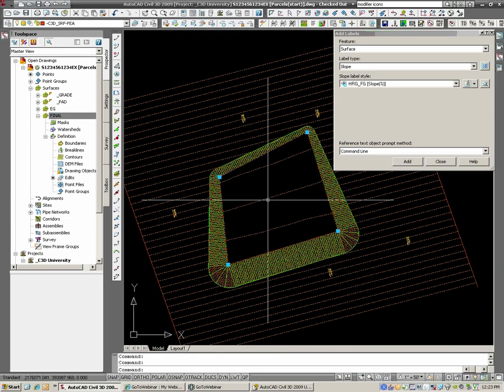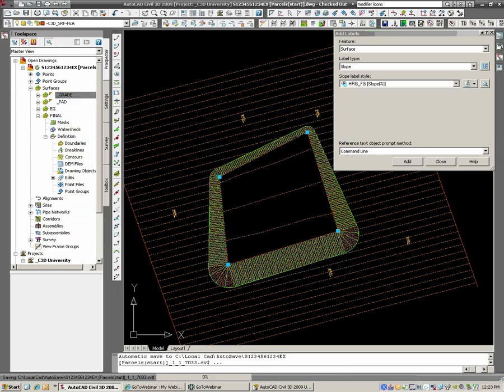And you can see it's all linked together in real time. So it's not like a solid paste where it happens one time and then you have to repaste it again. It's sort of linking surfaces together in conjunction. If I set these to automatic rebuild, set everything to automatic rebuild, of course, if I go and drag that pad around now, I get my autosave out of the way, everything updates automatically downstream.